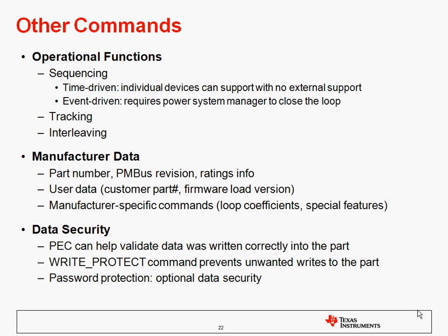Some other specialized commands that are available. Sequencing. Available is time-driven sequencing, where devices can support sequencing with no external support. They have timers that can be programmed so that from the time the on-off switch is enabled, you can wait a delay before ramping and then also set the ramp time. That's an open loop kind of sequencing. So it relies on the fact that every device before it has done what it was supposed to.